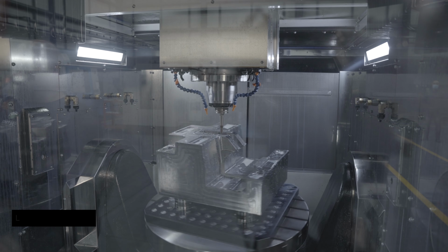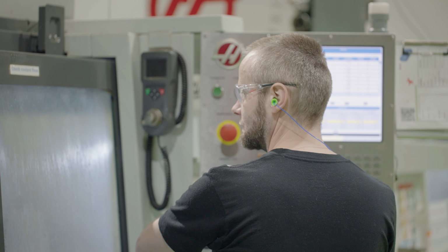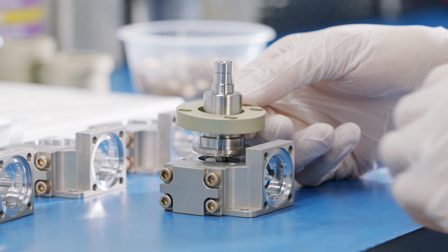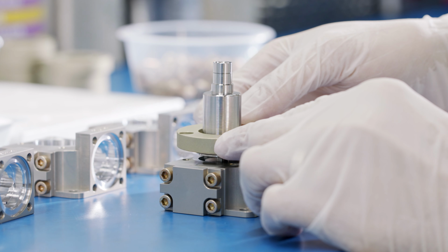Tight tolerances require more precise manufacturing processes, which increase production costs and time. So in order to fix this, you can define critical areas. Identify and apply tolerances only to critical areas where they're essential for the part's function. For example, a hole diameter for a press-fit bearing might require tight tolerances, while the other dimensions can be more lenient.